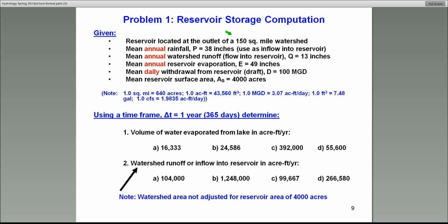Remember, the input of rainfall into a reservoir comes directly as a contribution, whereas the input rainfall into a catchment undergoes a transformation because you have to abstract losses in the form of infiltration, not just evaporation, evapotranspiration, and so on. So the loss mechanisms are different. A 10-inch rainfall on a watershed does not produce the same amount of runoff as the same 10 inches of rainfall directly into a reservoir surface system. There are no losses there except for evaporation.